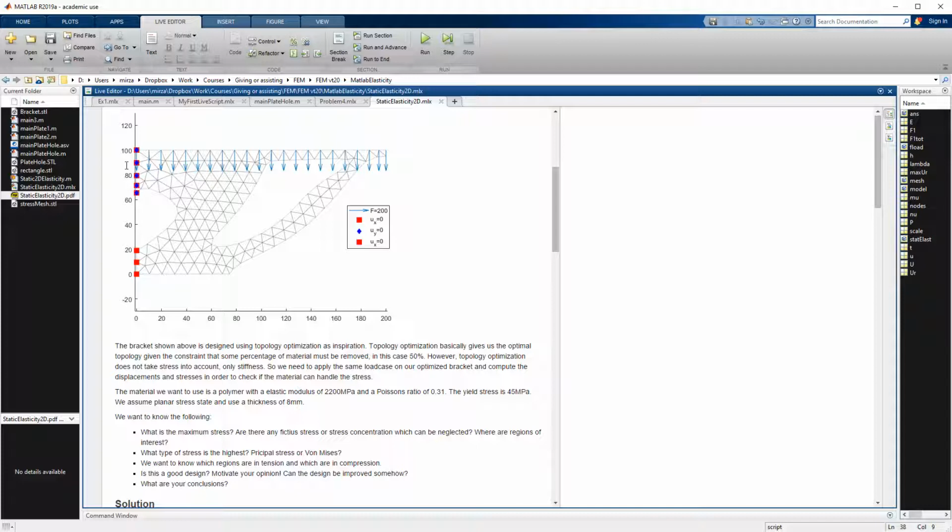are there any stress concentrations? If you have sharp corners, we have stress concentrations, and those are usually fixtures as well. And if we refine the mesh, they just tend towards infinity. In reality, we will get plastic deformation there, which of course reduces our stress. But assuming linear elasticity, we get very high stress at those regions. And they're typically of interest because we want to avoid these by changing the design.